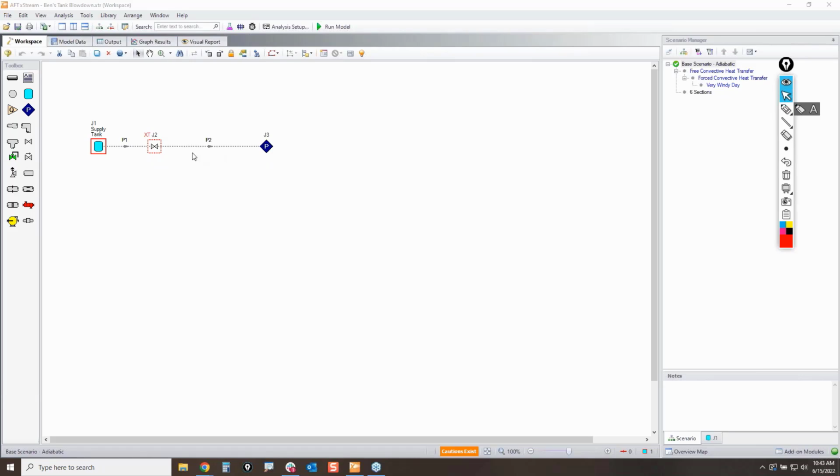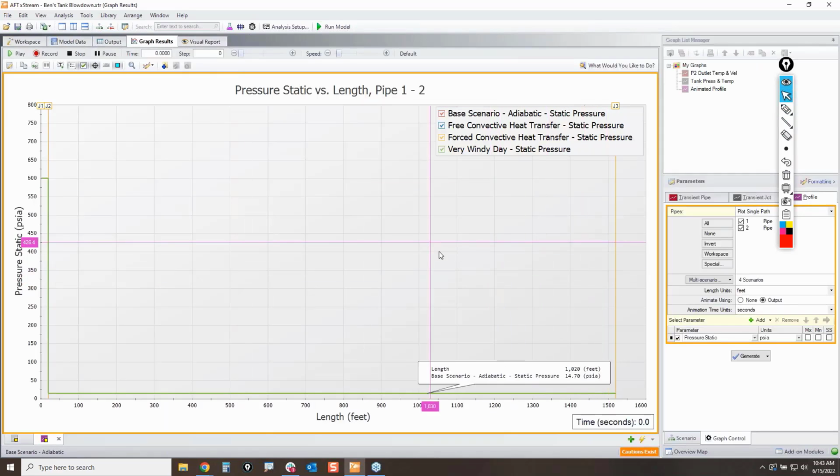It's similar to where Fathom does not yet model filling of evacuated piping systems. So same thing here. You wouldn't have an evacuated system, it would have air in it, but we don't have a mechanism yet that demonstrates that fluid interface boundary traveling down the line yet. So be aware of that when you get into your analysis.